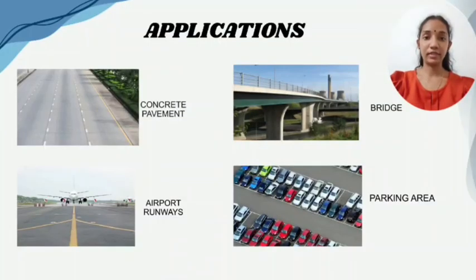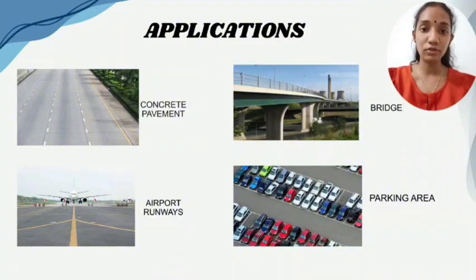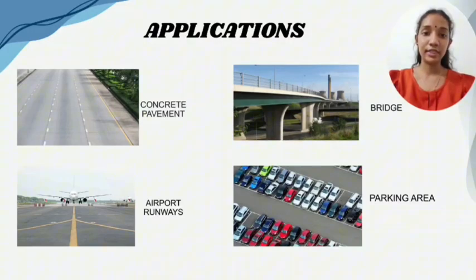Now we see application. Flexural strength testing is widely applied in many engineering projects. It is commonly used for designing and evaluating concrete pavements, airport runways, bridge decks, industrial floors, and parking areas. It is also important for assessing fiber reinforced concrete used in structures that experience bending loads. Engineers use the results of this test to ensure these structures can safely withstand service loads.